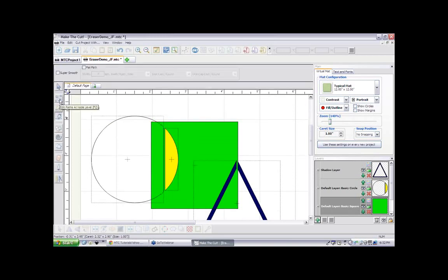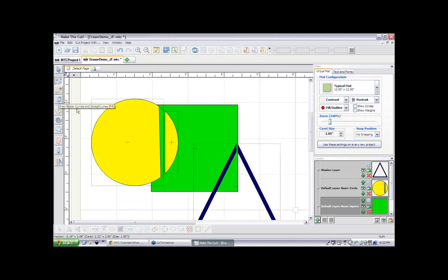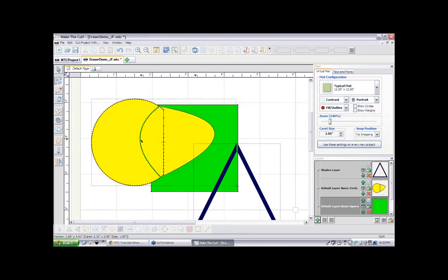Then you can click on the draw tool and left click here and then right click here, and you get a perfectly straight piece that has, and we'll check the nodes on this now, nodes only on the ends, where you have no intermediate nodes in here, and that would allow you to reshape your line, move it, edit it, all in one movement, which is a whole lot easier than here's our original line here. If you try to move it, you only can move in between nodes.